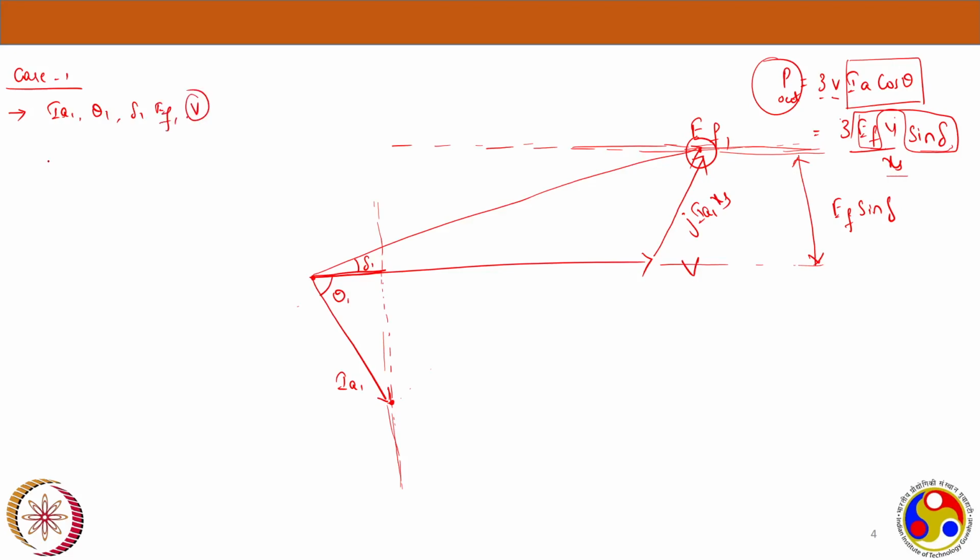Now what I do, I have increased the excitation. IF I increased. From the equation we have shown, if I increase IF, EF would increase. Both will change. My output power should remain constant anyhow, so the tip of the EF phasor must always lie on this particular line.